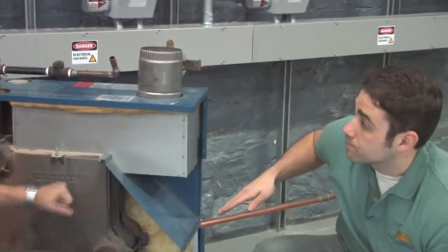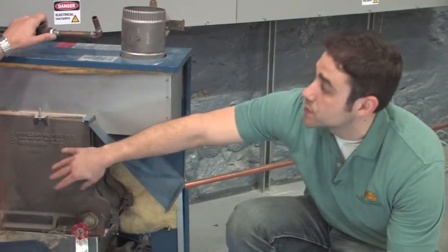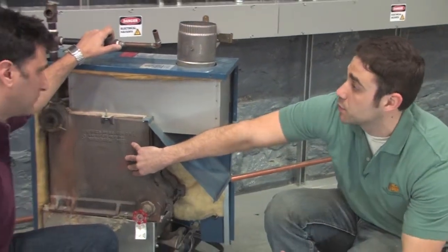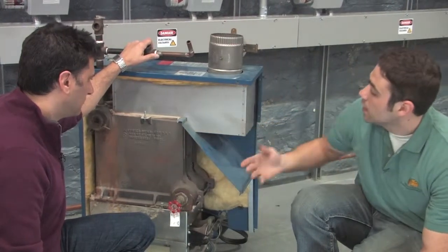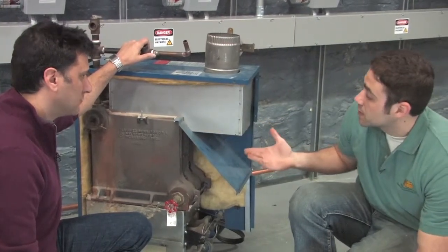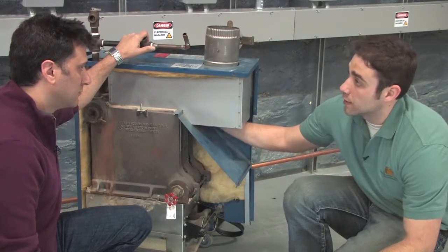And so this one's hot water? This one's hot water. This is a boiler system, right? So we have hot water inside here. We can either use this to circulate hot water, or this will actually produce steam as well. If you want to set it up to a steam system, you can do both. The difference is on this, when we test, we have dilution air coming in right through here. So we need to make sure we test before the air gets diluted.